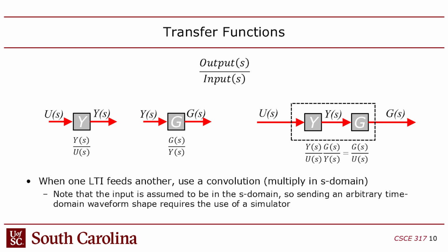It just has these signals or variables, functions of time, or functions of frequency in the case of Laplace, right? So in a transfer function, you represent this as a ratio, output variable divided by input variable. Usually you put that on one side of the equation. And then the other side of the equation is just a ratio of two polynomials of s. You guys with me?